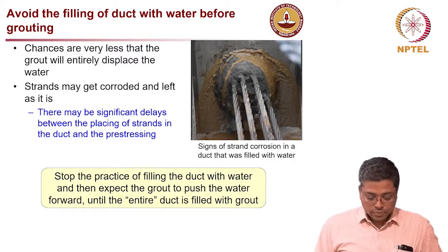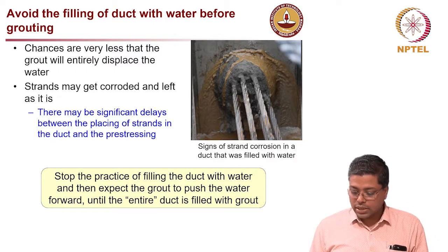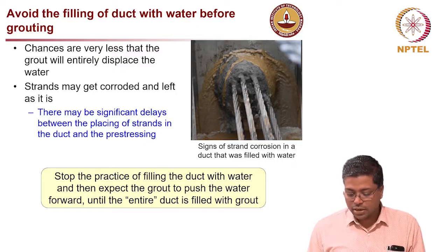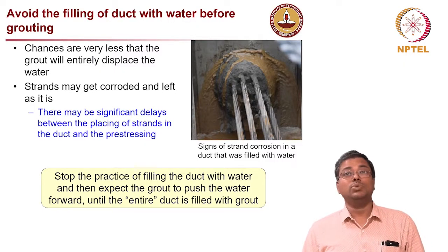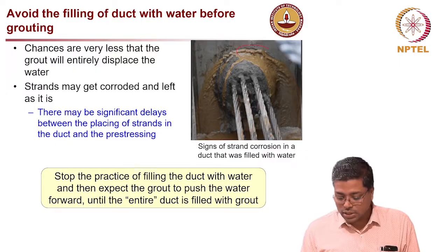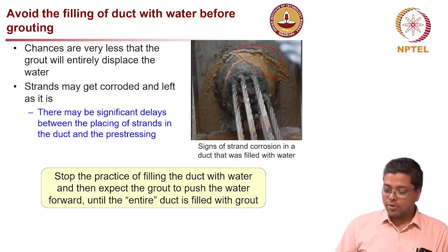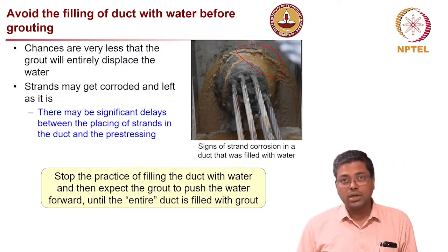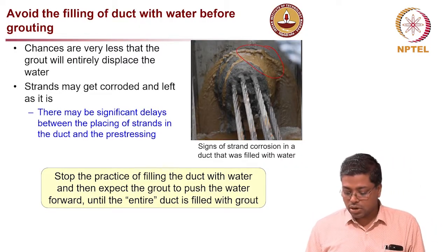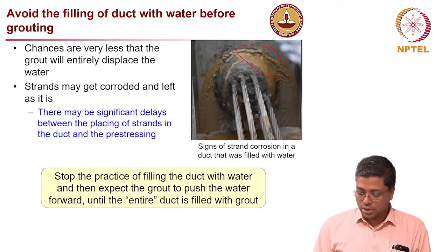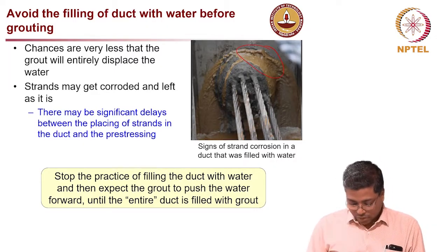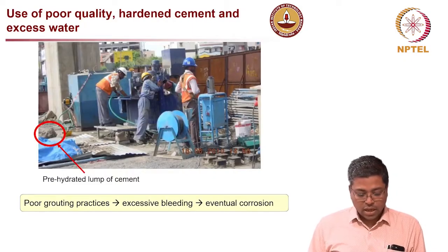Because of this, it is not recommended nowadays to fill the duct with water before filling the grout. Okay. You can see here, this picture was taken from one of the sites where this was actually practiced. As you see, the color of this grout is not gray. It has a lot of rust mixed with it. It is proof that the strand inside has corroded to some extent. So that is something which needs to be avoided.